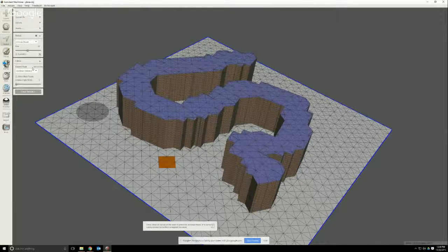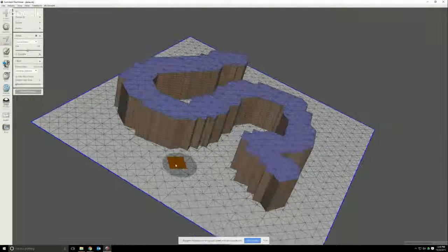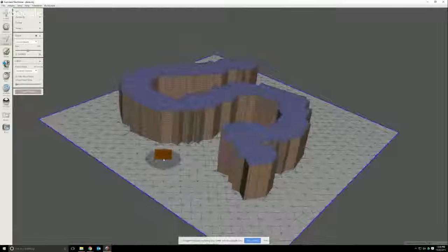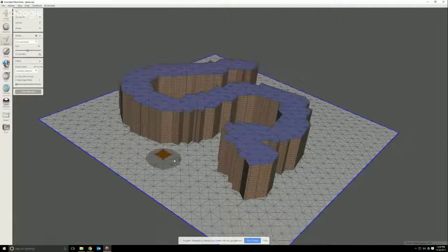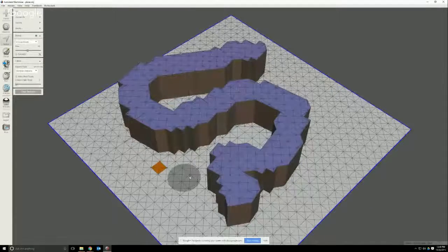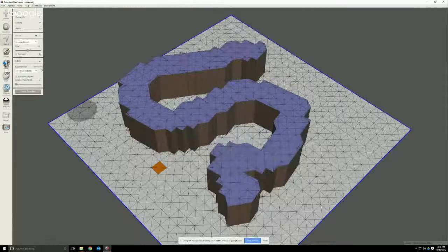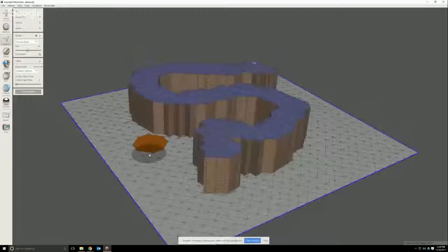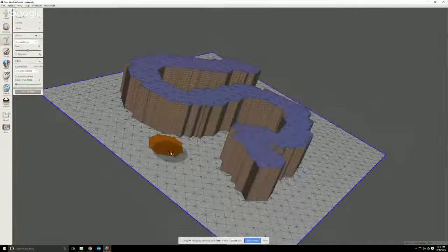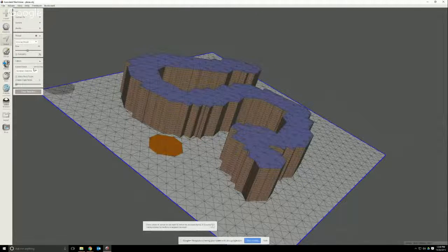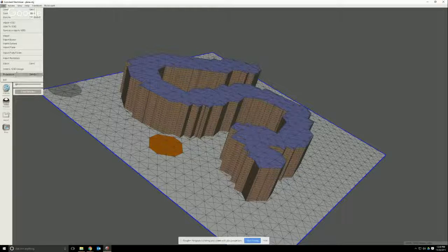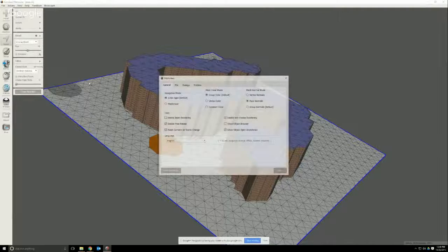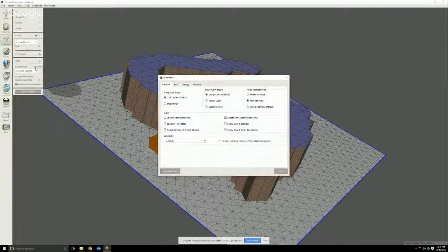And it says right-click drag. Right-click drag doesn't really do anything if you're using the default movement controls. So if you see right-click drag, you say, oh okay, but I am right-clicking and dragging. You have to hold down the control key in order to do that, so that should actually be control right-click drag. If you were using, up here under preferences, the navigation mode Meshmixer, then that would work as it says. But most people use the 123D apps.